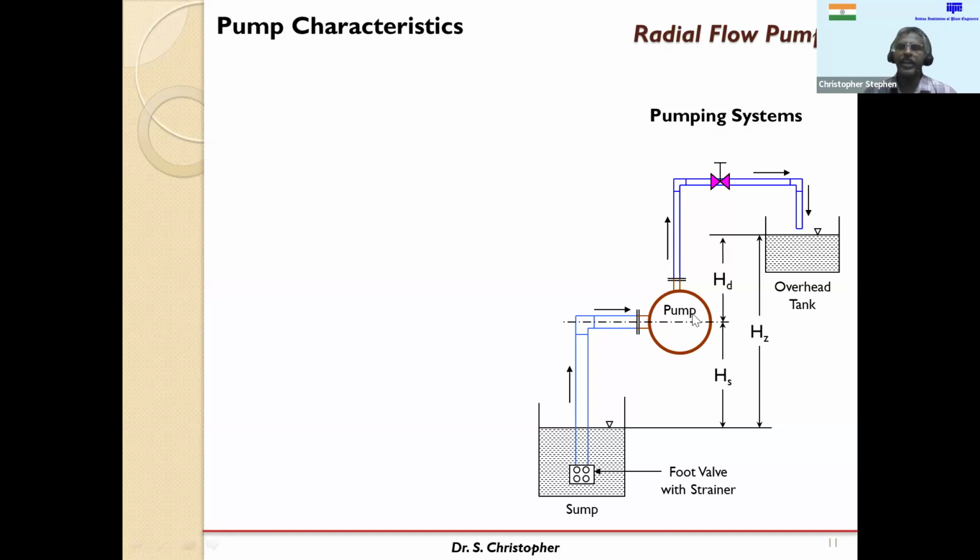And we all know total head is nothing but the head developed by the pump. If you want to be specific, total head is the energy at the outlet minus the energy at the inlet. Energy is the summation of kinetic head, pressure head, and datum head. These three composite are the energy. If I subtract the inlet energy from the exit energy, that is nothing but the head developed